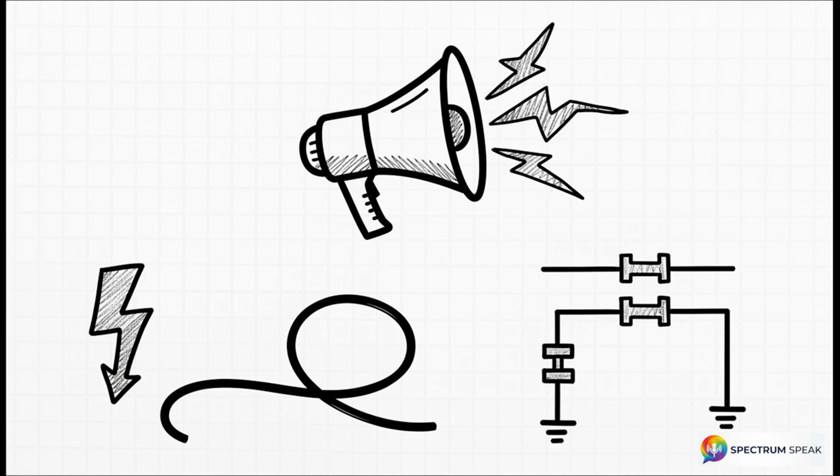Number 2, you cannot cheat physics. Higher data rates strictly limit your maximum cable length because the signal literally needs time to physically propagate for arbitration. And number 3, proper termination, ideally split termination with two 60-ohm resistors and a capacitor, is absolutely non-negotiable. Without it, the voltage simply cannot equalize fast enough and your network is gonna crumble.